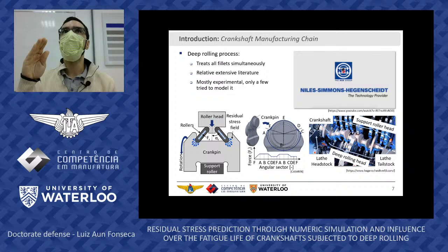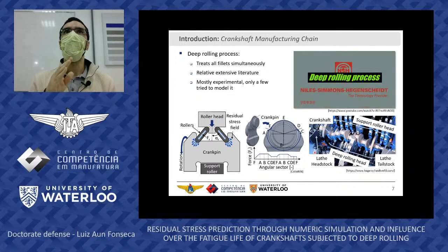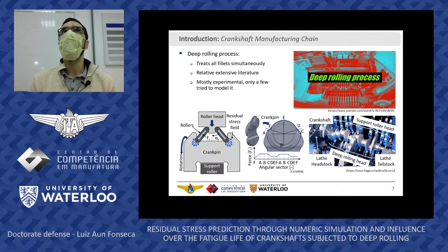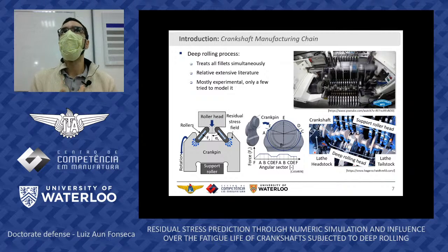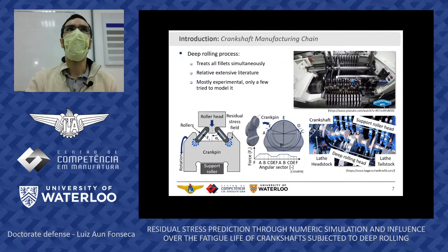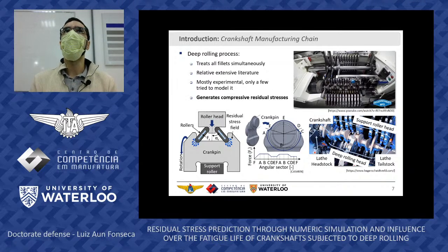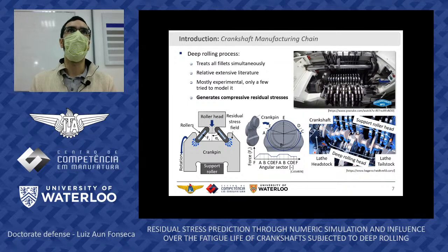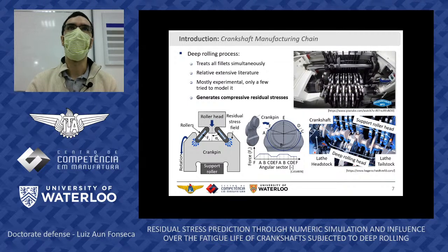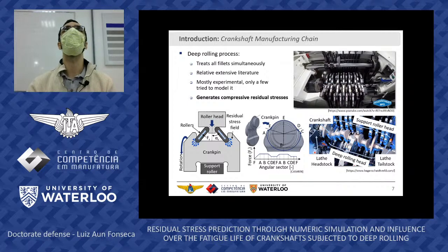So in the bottom part of the crankshaft, as you can see here in this graph, it is loaded with twice the force than in the top, and that is because we do have tensile stresses appearing at the bottom part when the engine is under operation. So this process aims at generating compressive residual stresses in that region to overcome these operational tensile stresses.